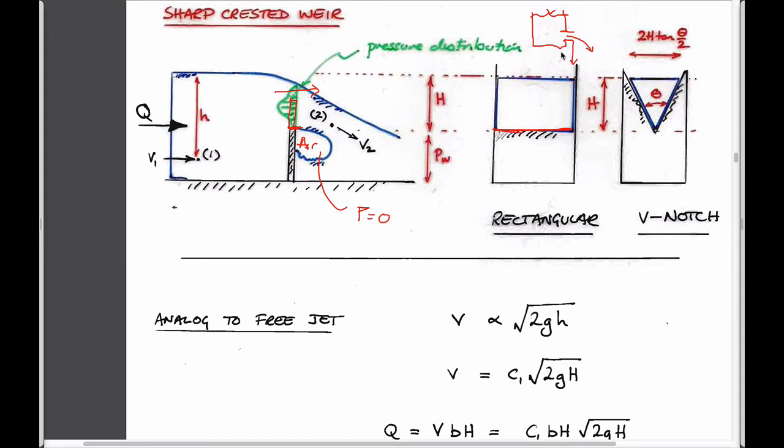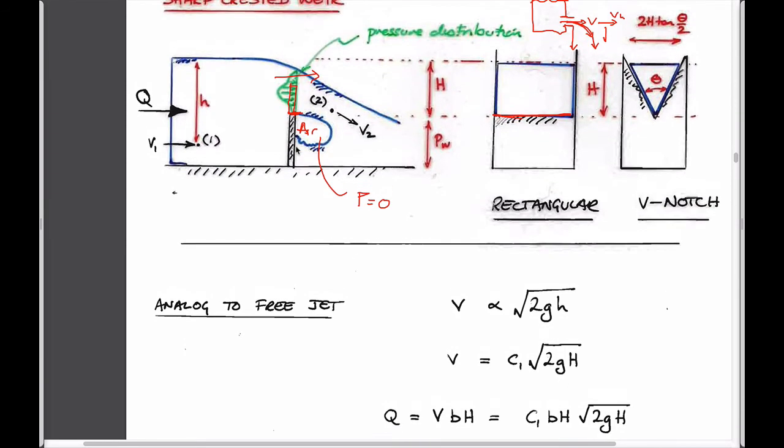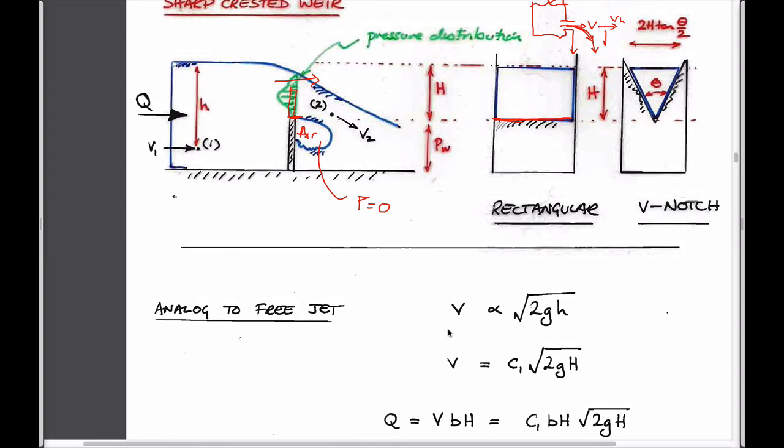Just by the fact that momentum is carrying it out of this because it has some velocity, and obviously it has a horizontal velocity, and as we saw last time or the time before, this horizontal velocity stays constant if nothing else acts on it, but it will also have gravity pulling it down, and that's why it takes this parabolic path. So there'll be a separation here. And so it basically becomes the expression that represents a free jet, which we've already seen before, proportional to some coefficient.